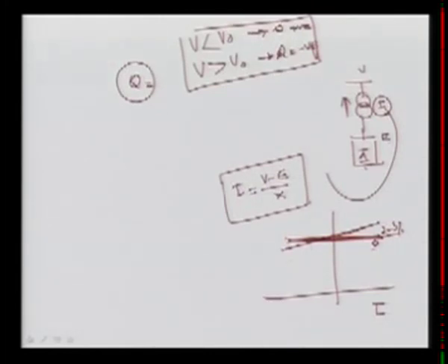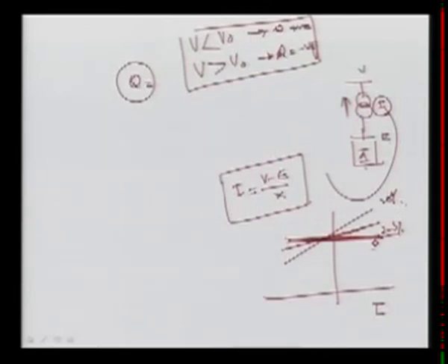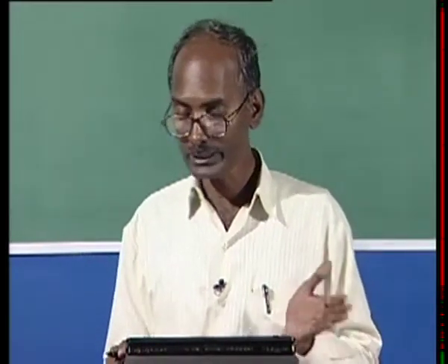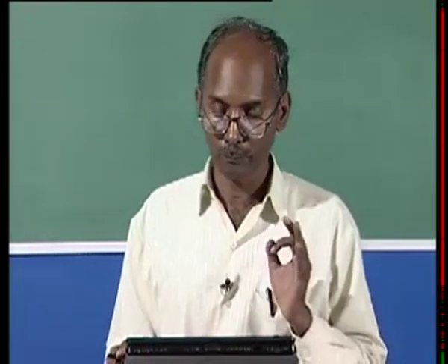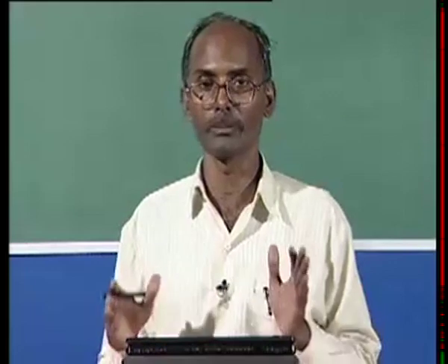But in the natural characteristic, this slope is 20% because the reactance of the transformer is very high. So the I or V characteristic is related to the reactance of the transformer. So we normally go for compensators having slopes of 2 to 5%. We saw the performance of both STATCOM and SVC, and we found that STATCOMs are better than SVC in several aspects: they improve the transient stability better than SVC if the limits are available.